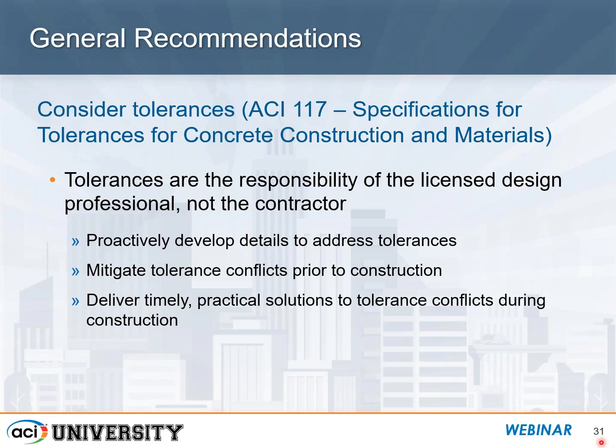Now, generally speaking, and this again is not true in all situations, and sometimes you can't help but do it, mitigating any tolerance conflicts in the field usually will be handled best by trying to manipulate the formwork in some way before, obviously, the concrete is poured.